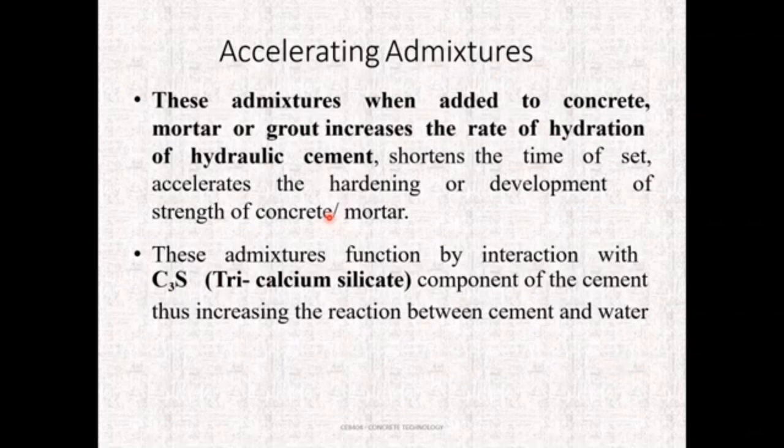The next one is accelerators. The admixtures which are added to concrete to increase the rate of hydration or shorten the setting period are known as accelerators. Here the action of the C3S, that is tricalcium silicate, is increased.